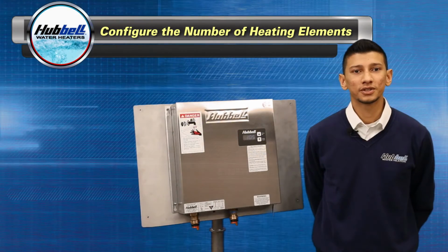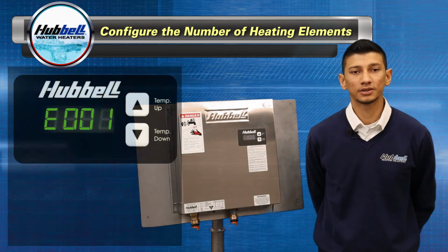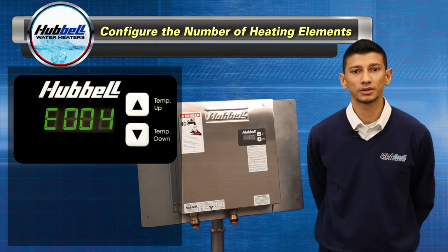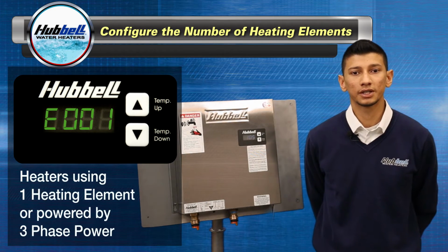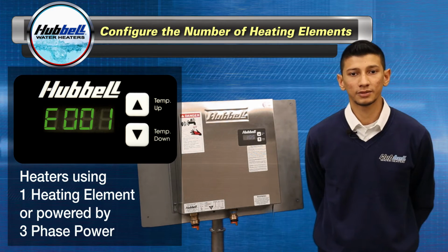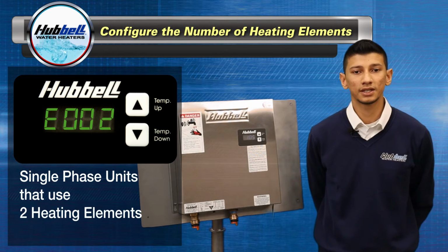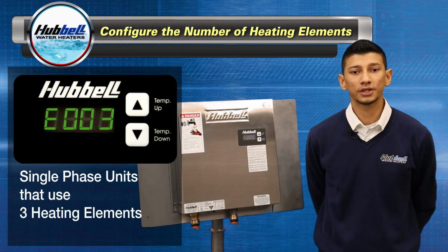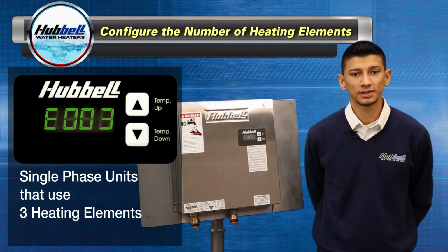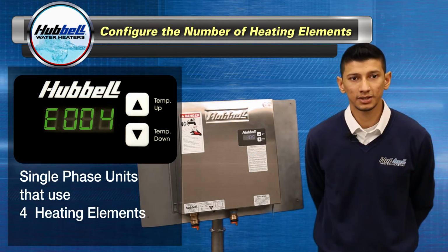The next parameter is used to configure the number of heating elements for your heater. There are 4 parameters available: E001, E002, E003, and E004. E001 is used for heaters that use only one heating element or heaters that are powered by 3-phase power. E002 is for single-phase units that use 2 heating elements. E003 is used for single-phase heaters that are powered by 3 heating elements. E004 is for single-phase units with 4 heating elements.